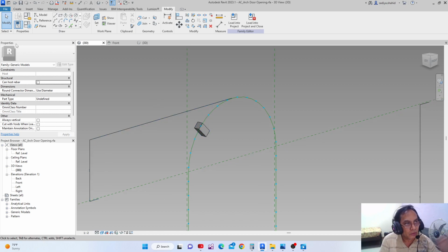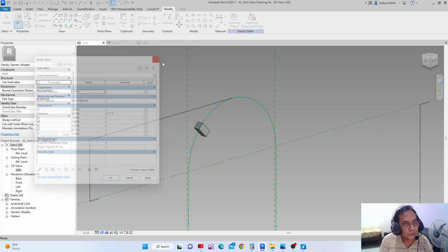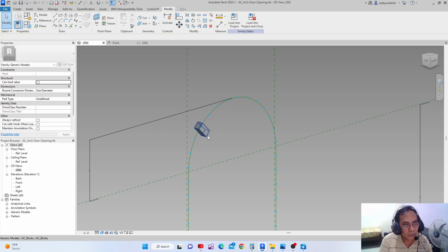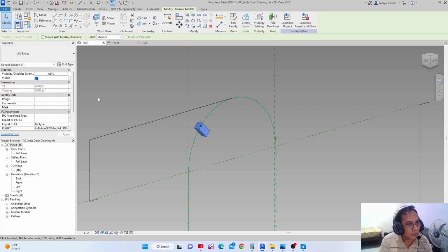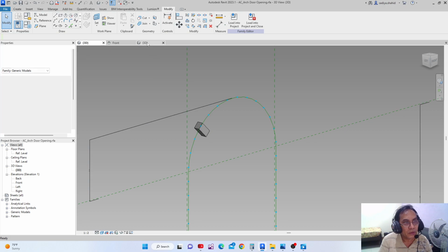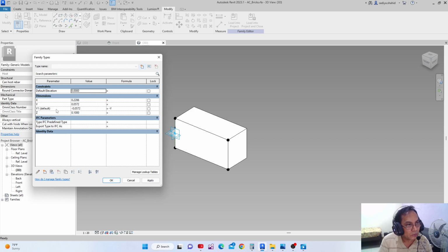We will change it here in our family type. First you select these bricks, and after selecting those bricks, you can associate. But I think the dimensions that we have created are not here. So what is the problem? Maybe it's not instance. So you need to go back to the bricks, and then you go to dimension, and you see y1 is the only instance here.